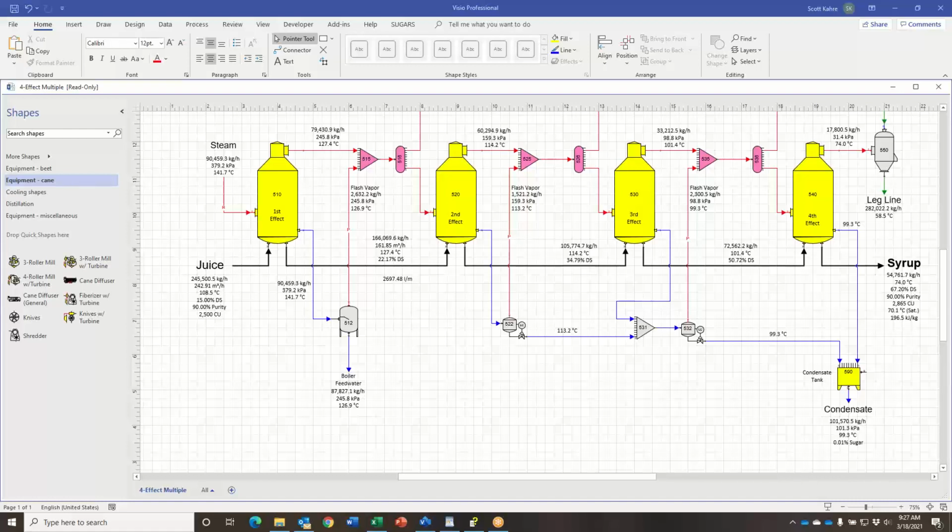Thanks for your question and your comments, Vic. And one more thing I want to mention on the evaporator boiling point rise. We do have some, and this is pretty distant future, but we do have on our list of development to add the ability to enter the liquid depth of an evaporator, so that then we can account for the static head boiling point rise if the liquid is leaving from a point at the lower part of that depth than the surface of the evaporation, which would be a different temperature. We do want to be able to account for that, but that's coming in a future release, probably in a couple of years.